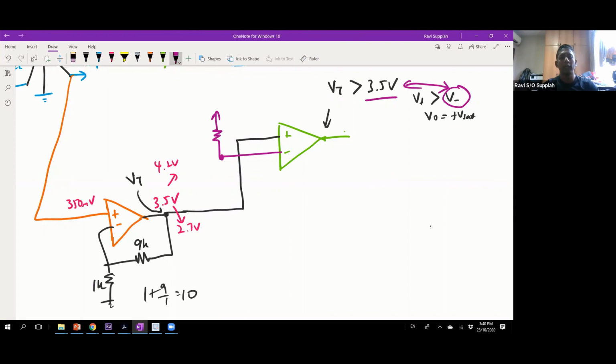Okay, I'm just going to connect two resistors, 1K, 1K, and I'm going to say that I have a 7 volt source. All right, so I'm just taking the easy way out. If you say you have a 5 volt source, then you choose two resistors such that you get 3.5 volts by voltage divider. In this case, I say I got a 7 volt source, so 1K, 1K means the voltage at the center here would be 3.5 volts.